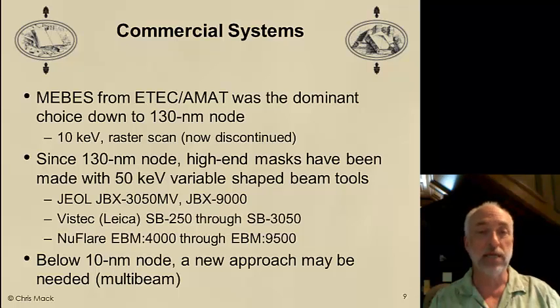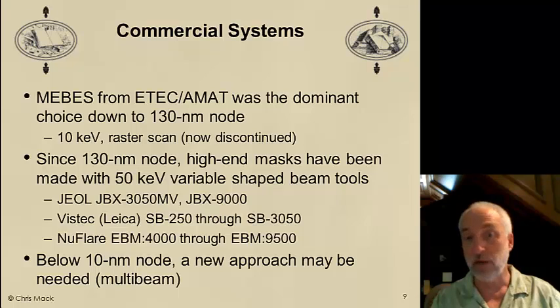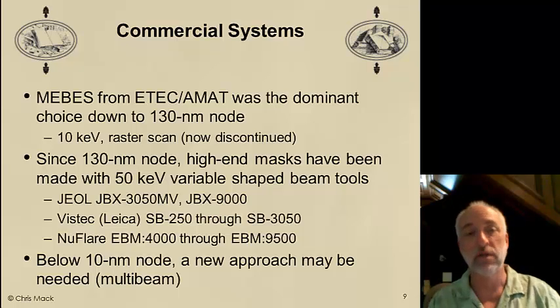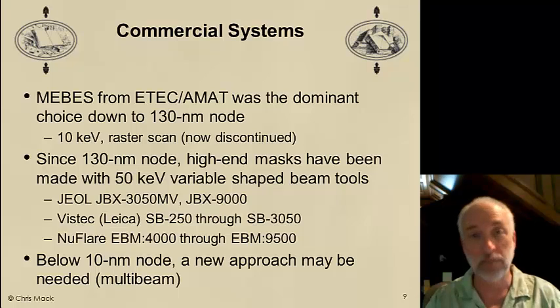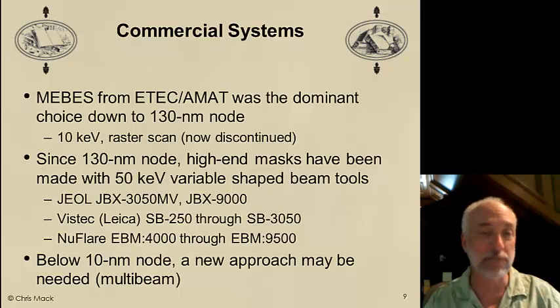So we've been writing for a long time now with the 50 keV variable shape beam tools from companies like JEOL, Vistec, which used to be Leica, and NuFlare out of Japan. These tools have been working very well, but we're starting to approach the limits of this resolution throughput trade-off for these tools, and below 10 nanometers we might need a new approach, multi-beam writing. We'll talk about that at the very end of this lecture.